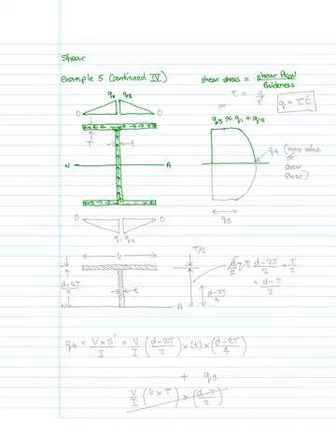So again, showing the arrows getting progressively smaller and smaller, and then in this case here, for the reasons we said in the first sheet, the shear flow is going to be in the opposite direction. So it's called shear flow because it's analogous to the flow of fluid going through the section.